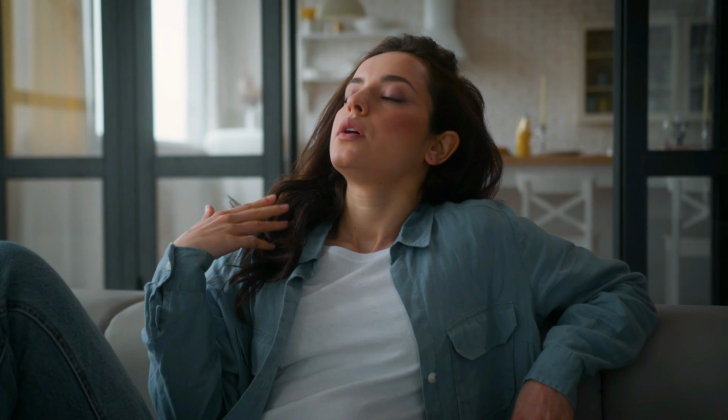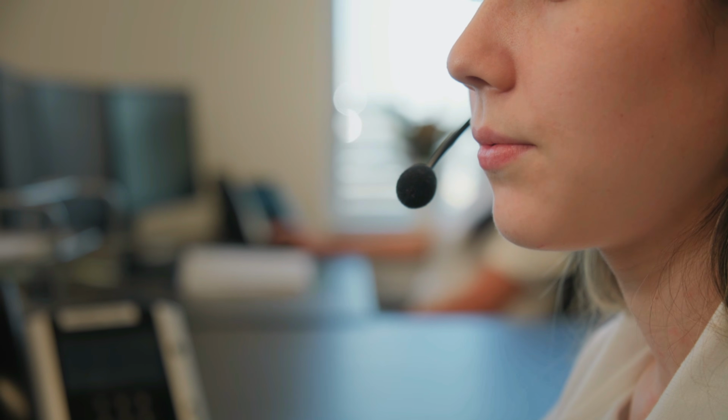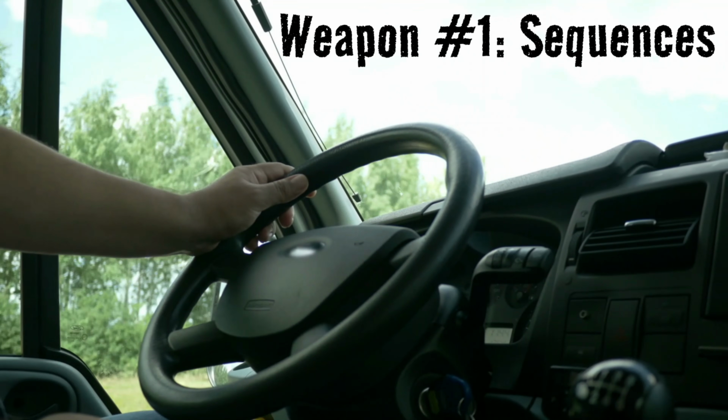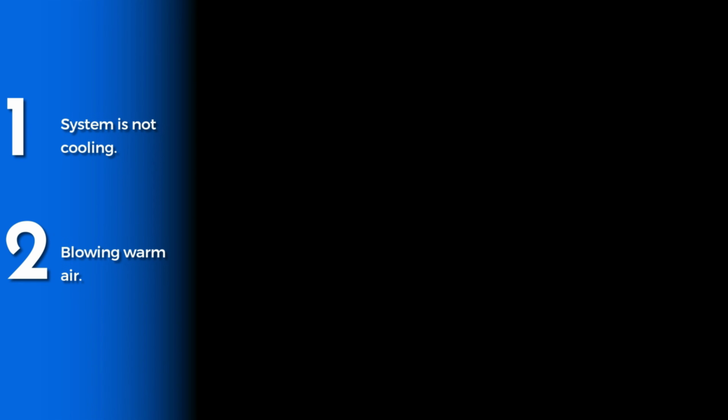So the customer calls the company, says their air conditioning isn't working, it's just blowing warm air. Dispatch conveys this information to you, and with this information you already have what you need to begin diagnosing through the sequence of operations, long before you even dispatch to the job. Let me show you how it works. So the 2 key things we know here is that the system is not cooling and it's blowing warm air.